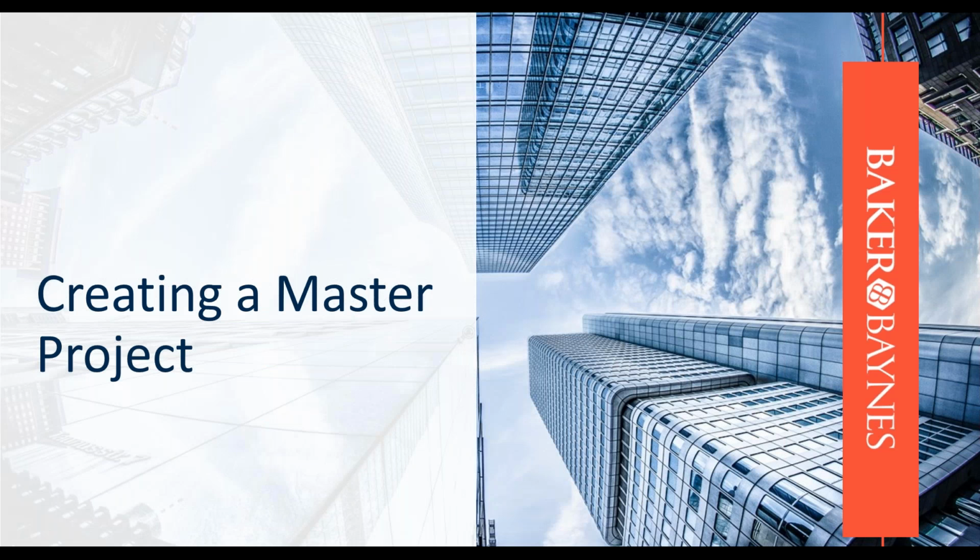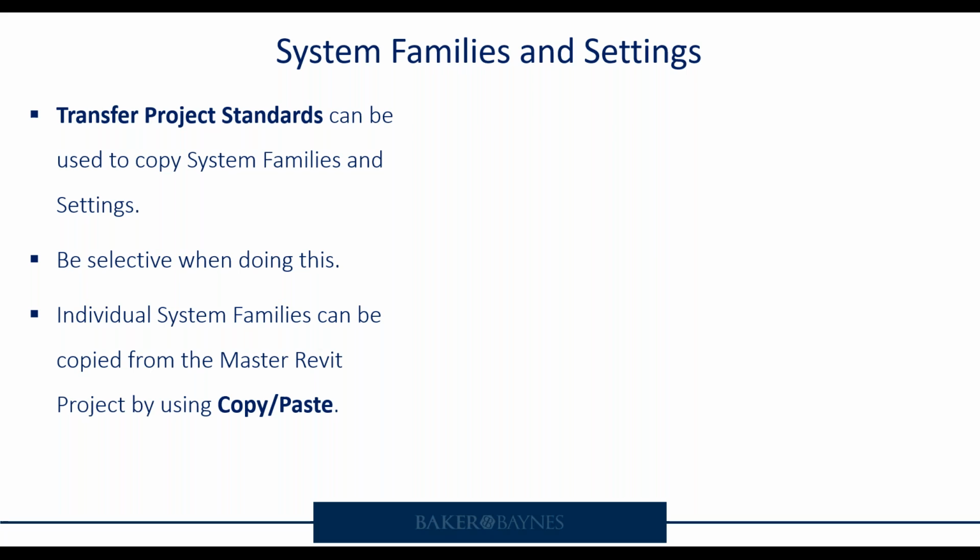Then, as I've mentioned earlier, one of your goals in creating a Revit template is to keep your file size as small as possible. So remember, the rule is that anything that's not needed in every project should not form part of your template. To assist with this, a good idea is having a master Revit project that contains all of the items that you may need so that you don't have to create them each time.